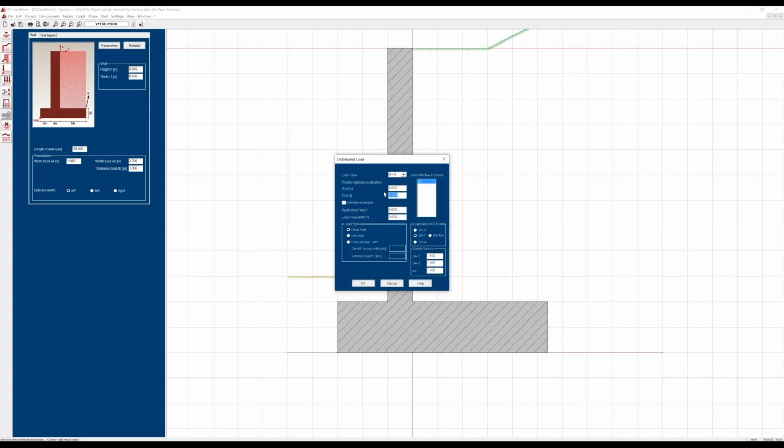So this is a kind of load case combination. And here we have a load value of 15, for example. This should be a live load. And so the safety factors are automatically adapted depending on the design situation, permanent, temporary, extraordinary.